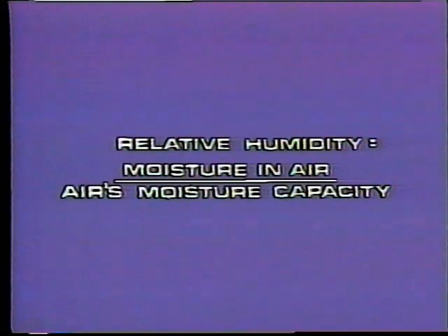Now, when air leaves an aftercooler, it is at a particular temperature, say 95 degrees. And at that temperature, the air is saturated with moisture. It's holding every bit it can. We say that it is at 100% relative humidity. Relative humidity is the ratio between how much moisture is in the air and how much it could hold if completely saturated. 95 degrees is the dew point of the air leaving the aftercooler.